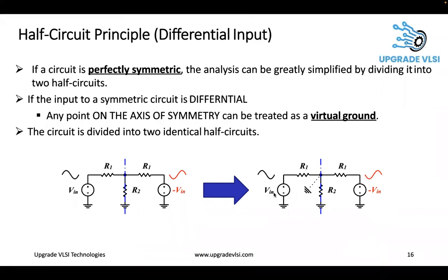Okay. So when this increases, it is basically pushing some extra current. Okay. And at the same time, this is reducing with the same magnitude. It means it is pulling some current from the same node. So the current which is pushed here is drawn from another terminal. Okay. So the current that flows in R2, nothing got changed. So all the current which is coming here, it is pushing to the other side. Okay. So there is no change in the voltage across this R2. So because of that, you can say that the change in current through R2 is 0. That will happen only when the other terminal is ground. And please note, it is an AC ground. So I am talking only about the changes.